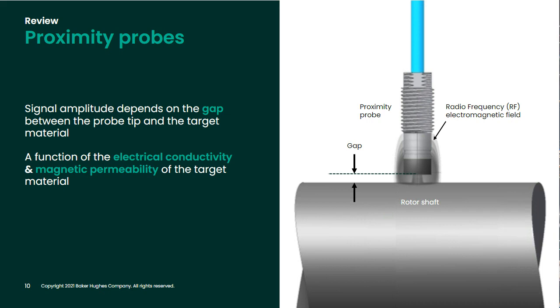This is important to understand when utilizing prox probes in a monitoring and protection system, and highlights the importance of understanding and mitigating runout. Proximity probes are very accurate and very detailed, but as such, they'll also pick up any inconsistencies. So care in the preparation of the shaft is of the utmost importance.